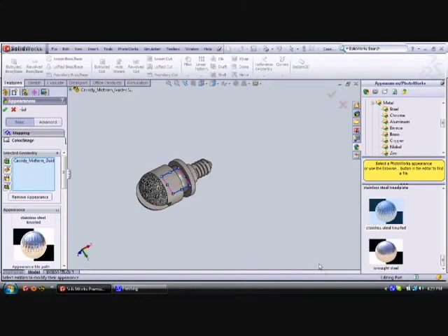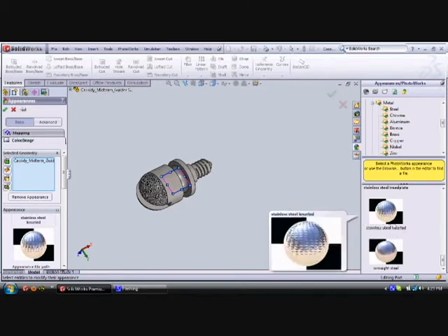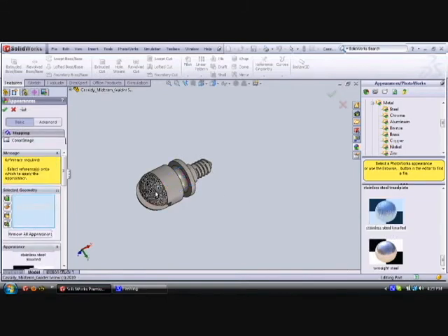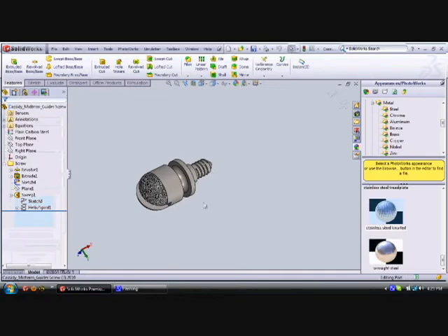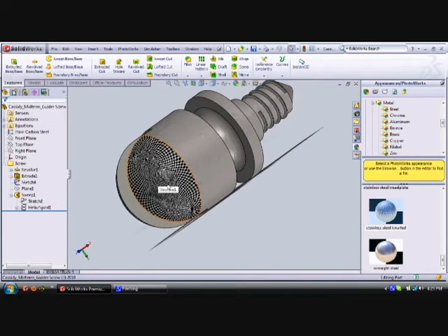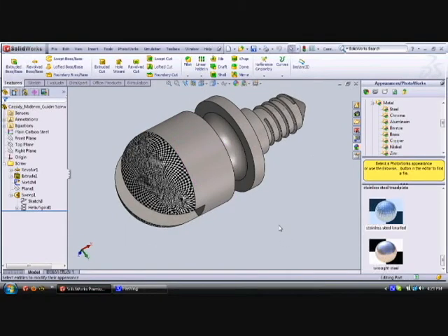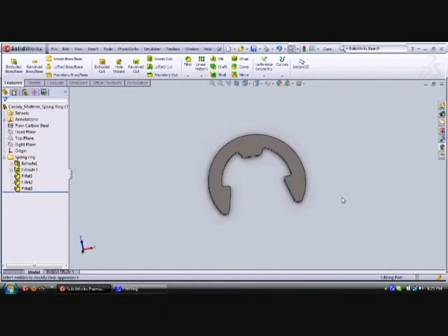One of the challenges I faced while designing this product was showing the knurling on the top of the screw. While SolidWorks does have a stainless steel knurled effect listed, for whatever reason it doesn't actually use it. To get around this, I just used a checkerboard configuration to show that a knurling effect would take place there.